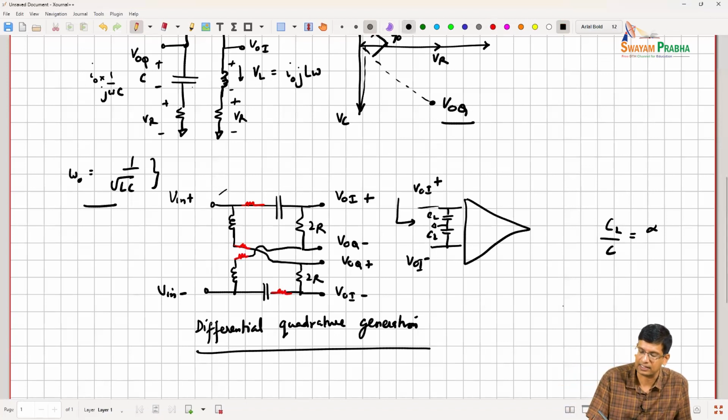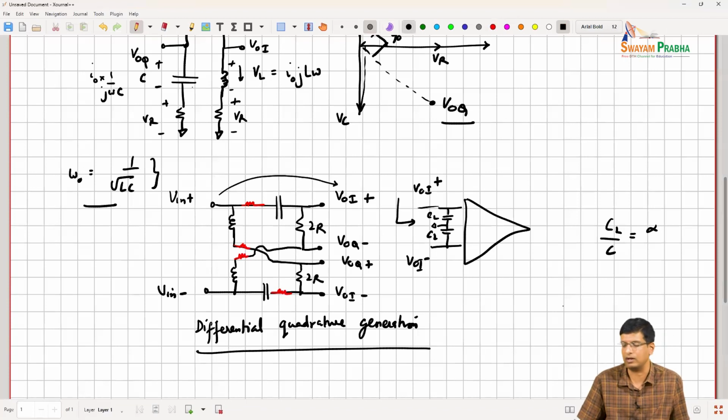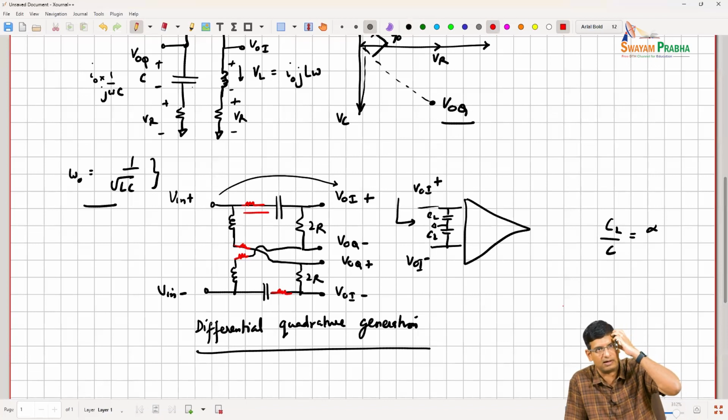So in the ideal scenario, from here to here, when you analyze this, you see that there is basically a gain of 1 over square root 2 or 3 dB. There's a voltage gain, right? Passive gain as we discussed before. But by applying this resistor in here, we are going to see a little bit more attenuation. So the loss is going to increase, but then the bandwidth is also going to increase. So that trade-off you can make depending upon what your load looks like.